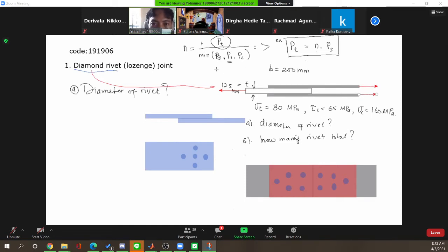So 5 rivets will be on the left side here in this overlap joint. So 5 is here. And the right side also has a similar situation. If we remove this left plate and pull the right plate, then it has also the same load state like this.